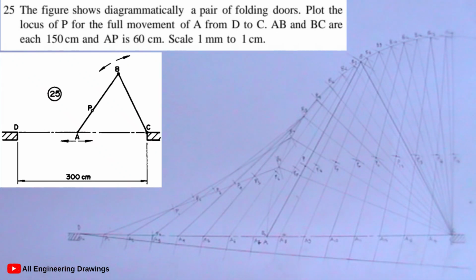So after marking the points, that is the P points, after numbering them, so we draw our curve to pass through points P0 down to P15. So I'll be doing so using my French curve.